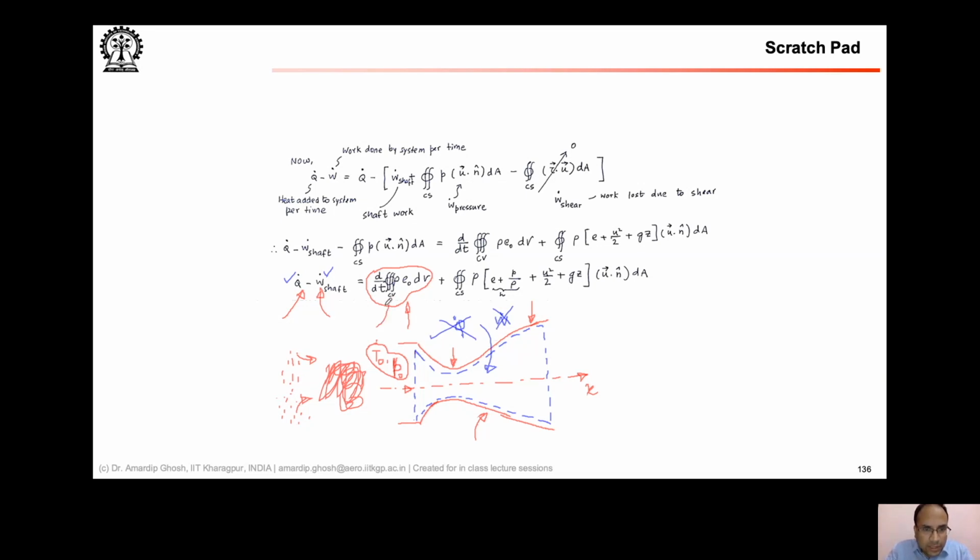So then if this becomes 0, at this point for this nozzle problem, for the compressor, flow around the compressor, flow around the turbine, flow through the combustor, things are slightly different, right? For the flow through the combustor, you will of course have a Q dot term. However, in this case, this has become 0, this has become 0, this has become 0. So now what happens? What is happening on this side?